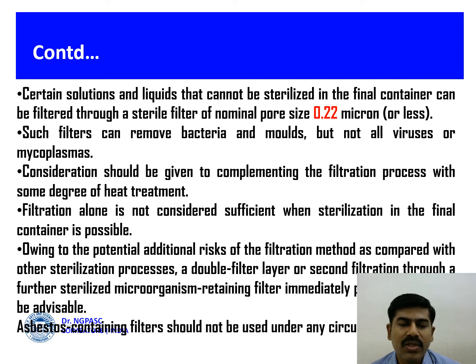So certain solutions and liquids that cannot be sterilized in the final container can be filtered through a sterile filter of a nominal pore size 0.22 micron or less. So such filters can remove bacteria and molds, but not all viruses or mycoplasmas. Consideration should be given to complementing the filtration process with some degree of heat treatment. Filtration alone is not considered sufficient when sterilization in the final container is possible.